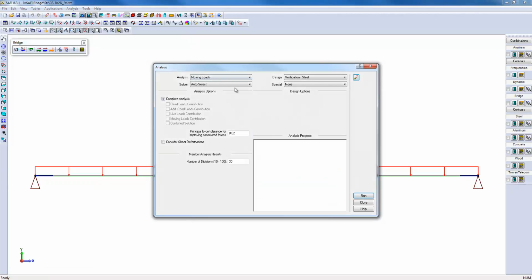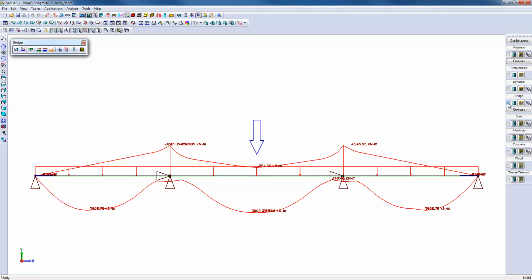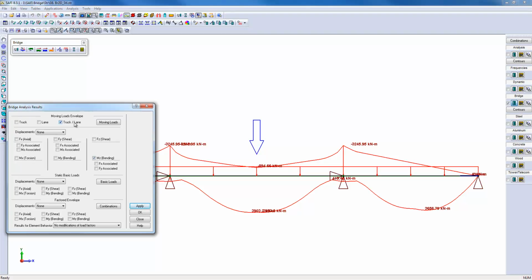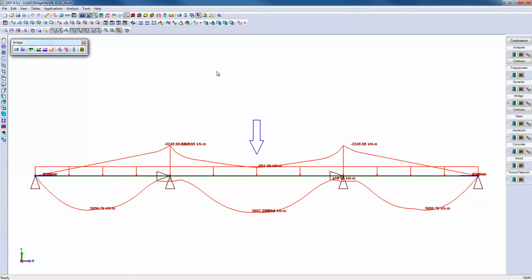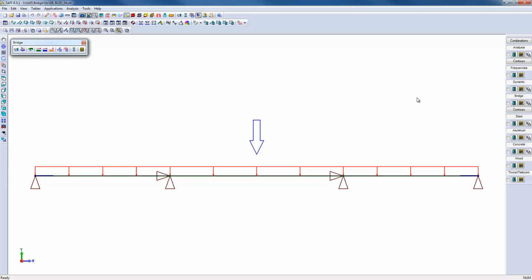We can go ahead and run the moving load analysis. For example, one can go visualize the bending moment caused by the truck. We can then associate the different lateral distribution coefficient to the beam of the second span to note its influence on the bending moment curve.